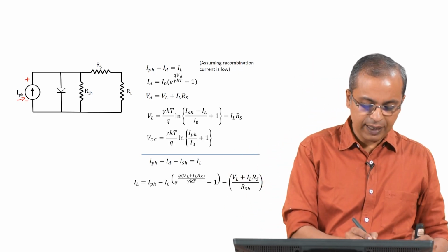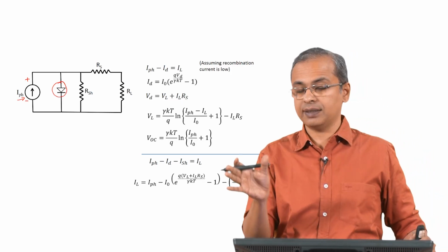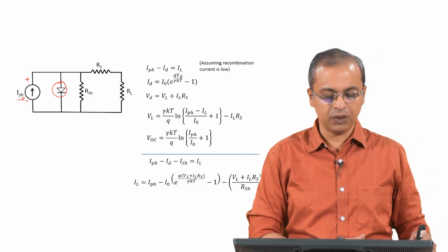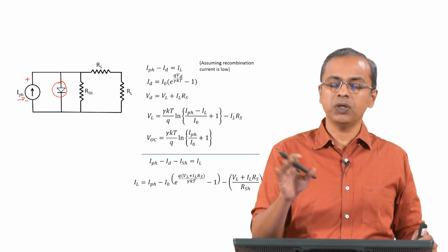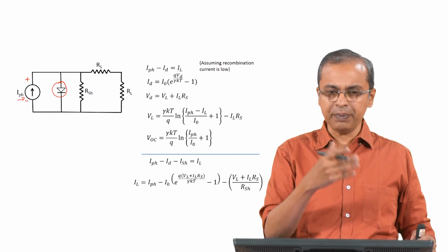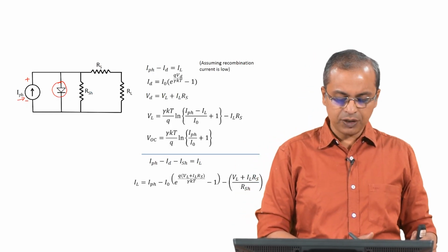So this is that diode that we are talking of, internal to the solar cell. This is not an external circuit, this is internal to the solar cell, right. So this is a forward biased diode, and so some amount of current will flow through the forward biased diode and internally get consumed. We do not want that to happen, but that is what is going to happen. Some will always happen that way, okay.